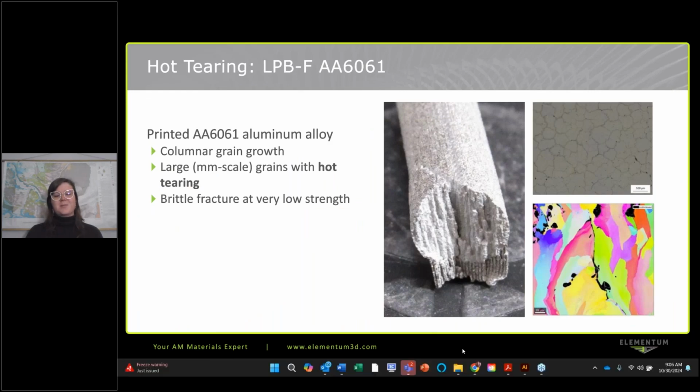So jumping right into our aluminum materials, for those of you who may not know, aluminum is not something that's easily printable off the shelf for additive manufacturing. There are a few select casting alloys that, when additive first got started for metals, we were able to print outright. Many of you probably are familiar with AlSi10Mg, right? However, if we go to use some of our wrought materials that are higher strength and particularly precipitation hardenable, things like 6061, 2024, 7050, we can't really take these base powders and print with them.